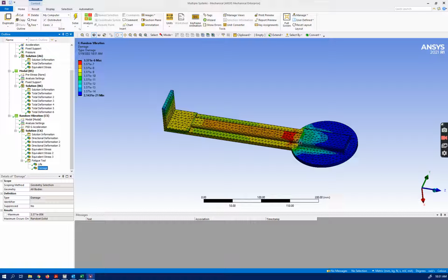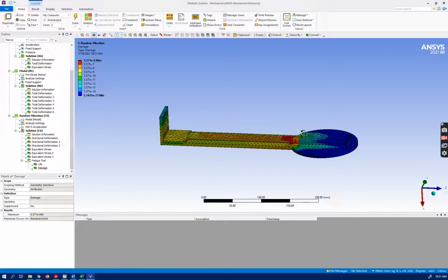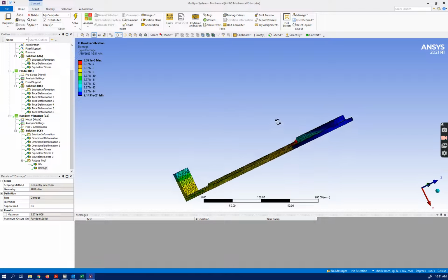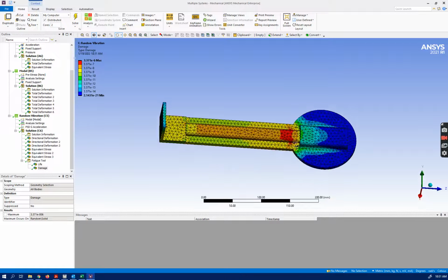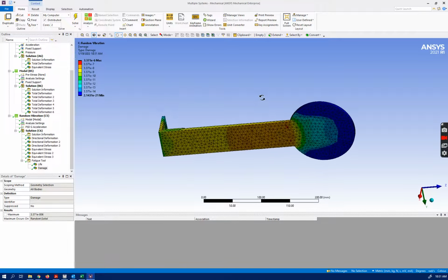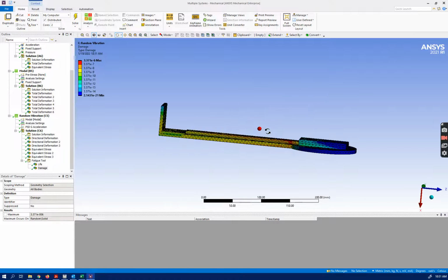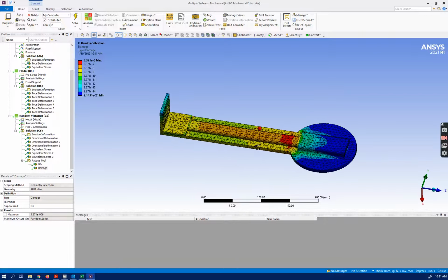Okay, we are going to have damage mainly in this area, and I need to make sure this area is a little bit stronger, maybe add more material here and make it a little bit thicker. And of course I need to improve the mesh quality to have better data, but probably the weakest area for this mobile holder would be this area, which we need to investigate.